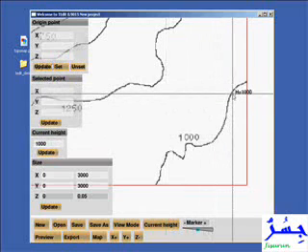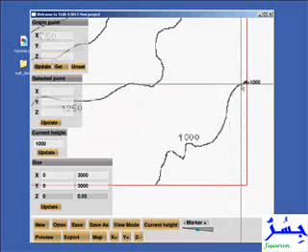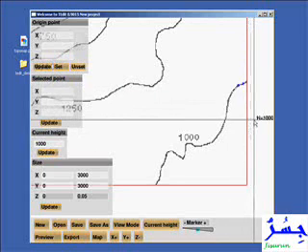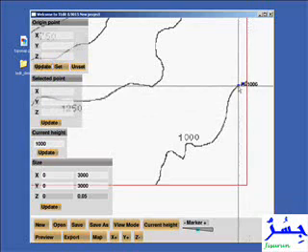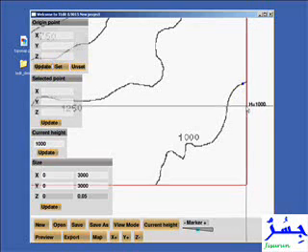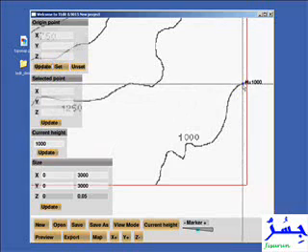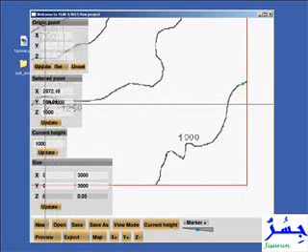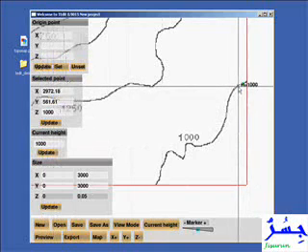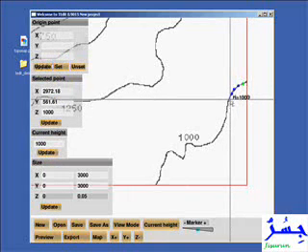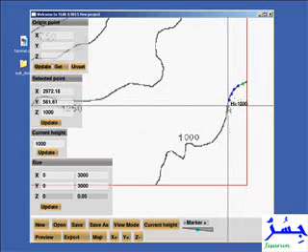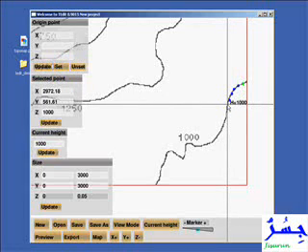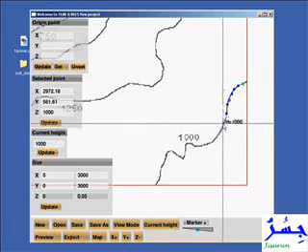Now to actually add points, you use the left mouse button. If you click on the mouse button once, you'll have your points added. If you click on the same point with the right mouse button, that would delete the point. If you click on the middle mouse button or on the wheel mouse button, that would give you the point's coordinate. Obviously just clicking would also work, but another feature that also exists is you can click on the left mouse button and keep holding, and as you move, the points will keep on getting populated.